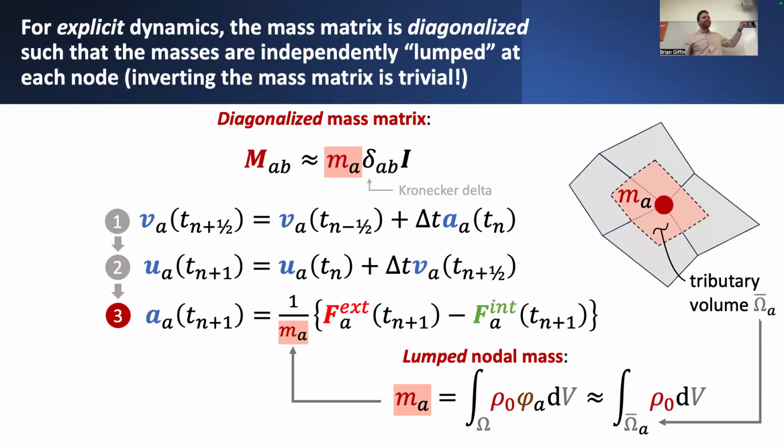If I'm assembling this mass matrix, ordinarily it would be a matrix that might have a block diagonal form or something like that. In practice, there would be some non-zero entries on the off diagonals, and it would at least be compact. It would be banded. It would have all these other nice properties that we're familiar with as they pertain to finite element stiffness matrices.